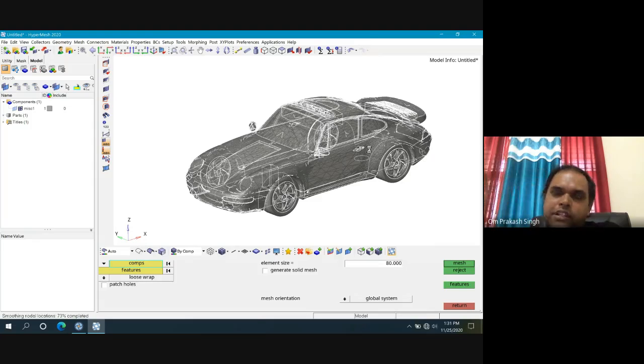They will take their mobile, and there are some guidelines on how to take pictures of that design. If there's glass, you cannot take an image of glass properly. So you put some feature curves, make a cross mark, or put a newspaper on the glass. Introduce some additional features so that the camera can identify them while stitching the design.